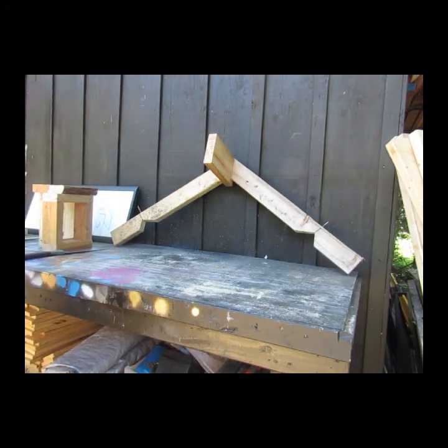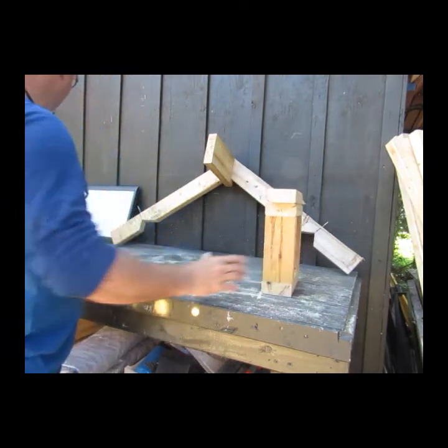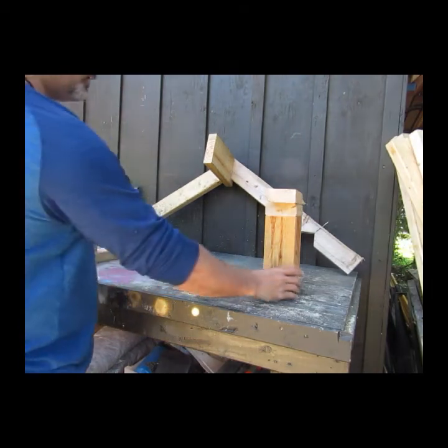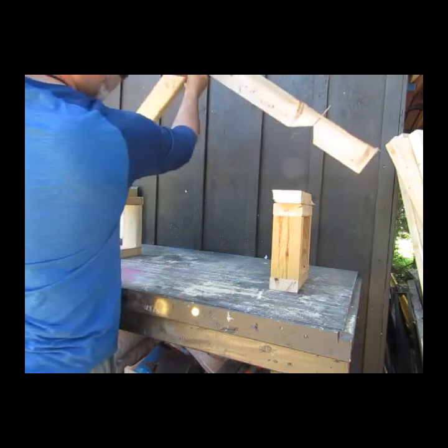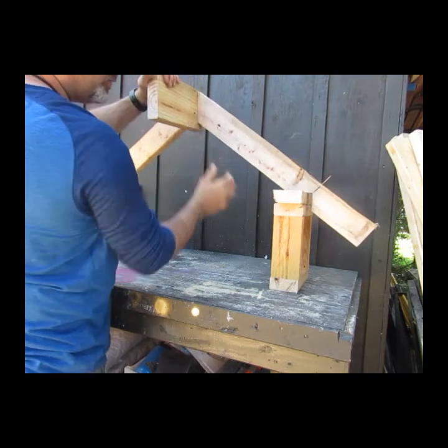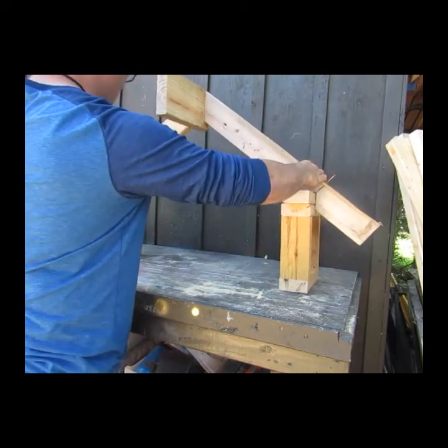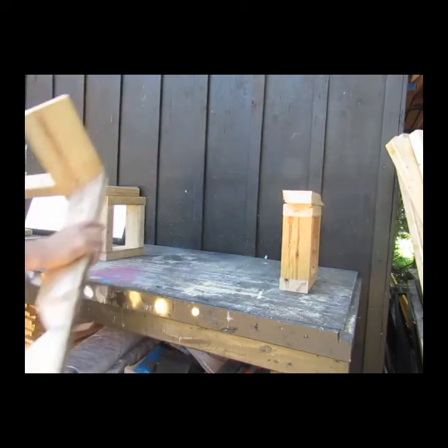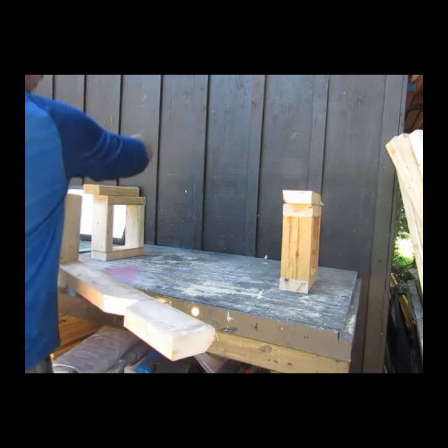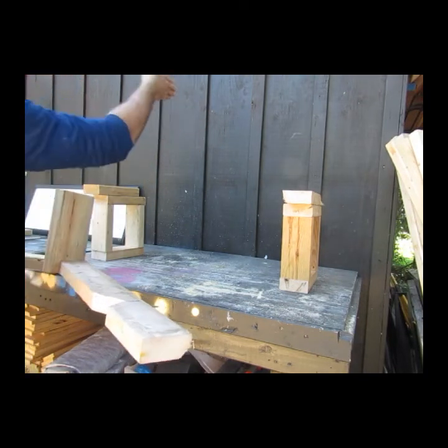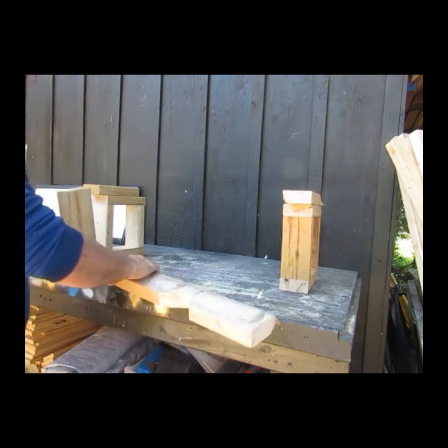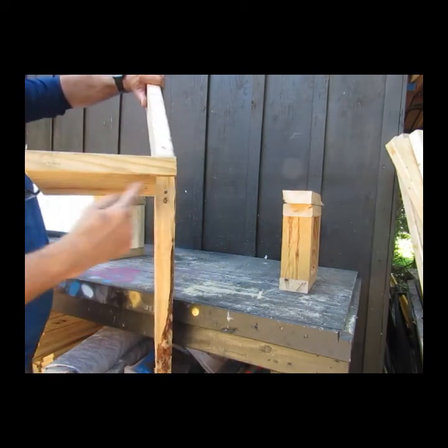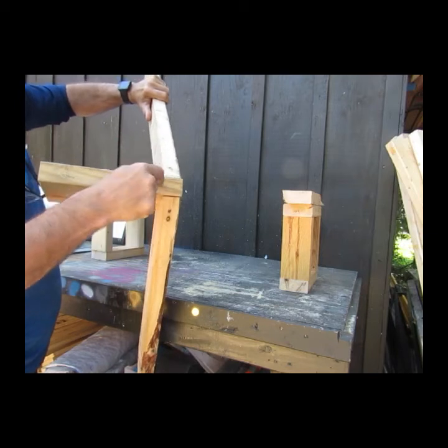So here is what I've also got: a left wall and a right wall. Here is our rafter system, which doesn't go together and get put in place all at once. It goes together one piece at a time. These walls would be in place, and you would structurally support, at the far end, a 2x6 ridge beam. Then you would start taking each rafter, putting one rafter up, the other rafter up, at the same location. You can't stagger them because they actually reinforce each other across the ridge beam.